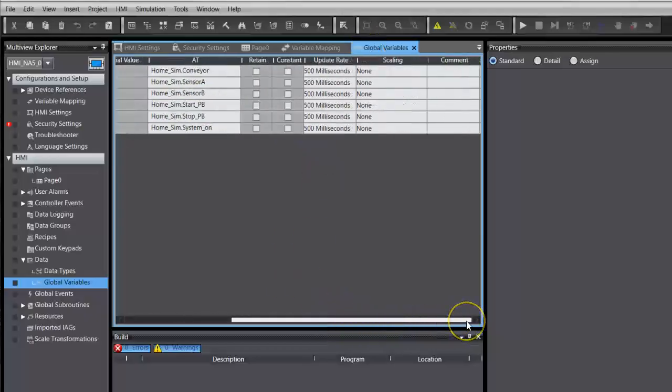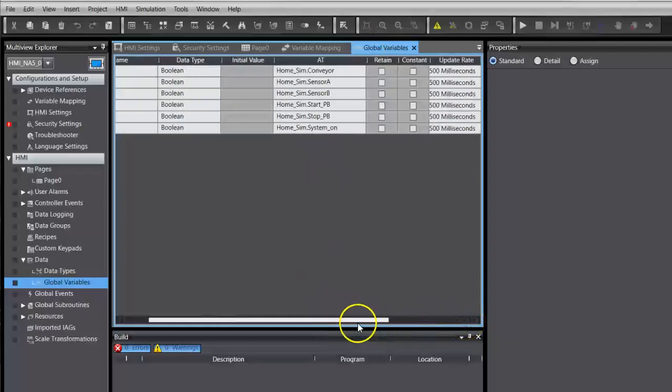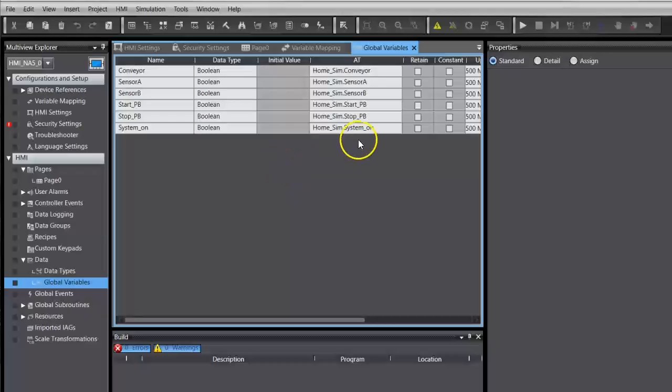There are other settings, the update rate, half a second, 500 milliseconds. So it's not, as PLCs go, it's not fast. But the HMI is basically something just for humans to use, human-machine interface. So the speed, we don't work nearly as fast as machines do, so the speed isn't all that critical. But that's a spot to check.